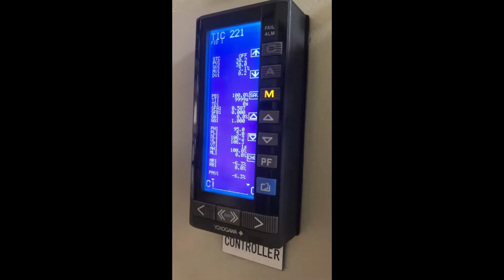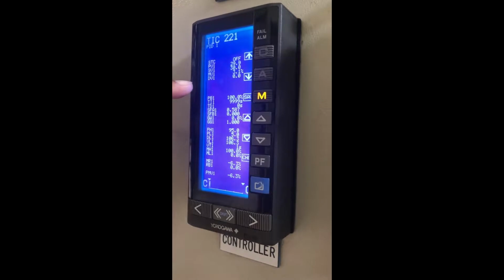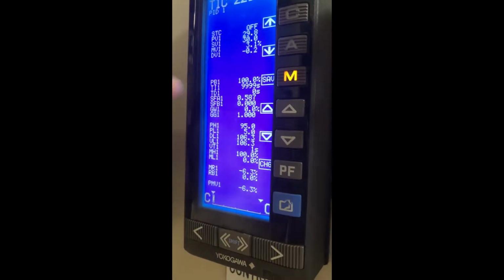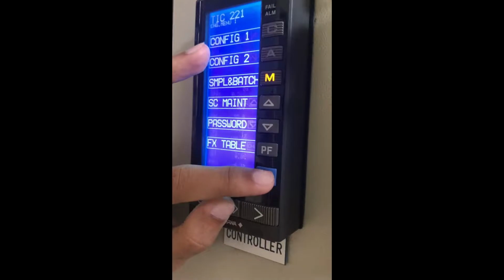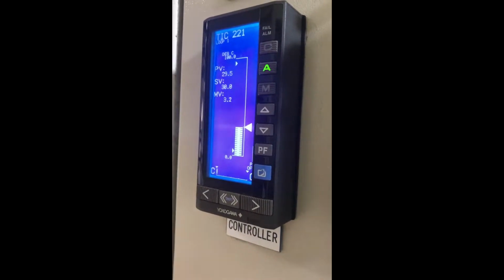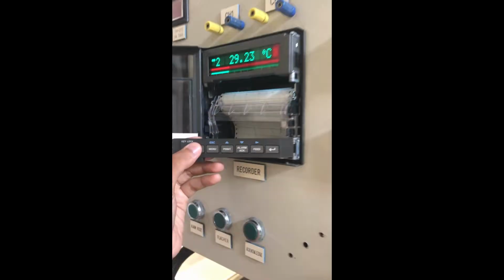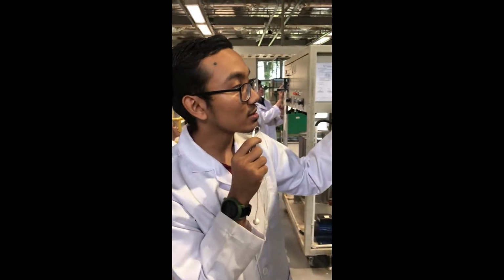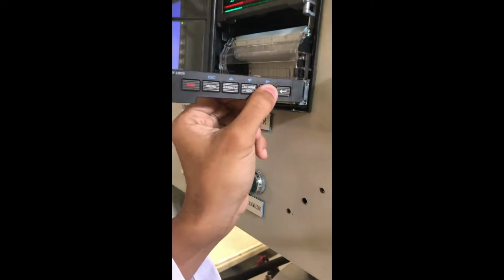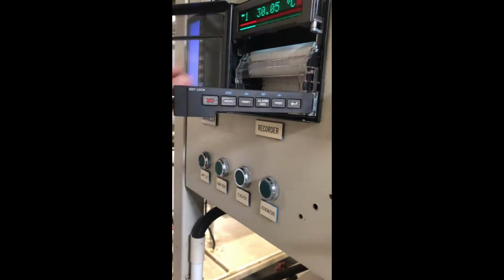According to the data that we want, we edit the values for the P and I and also derivative here. When we have set, we put this system to auto, and we let the system stabilize and get the record. Not to forget to press the record button. When we have done our part, just press this to make it go a bit far, and we tell the result.